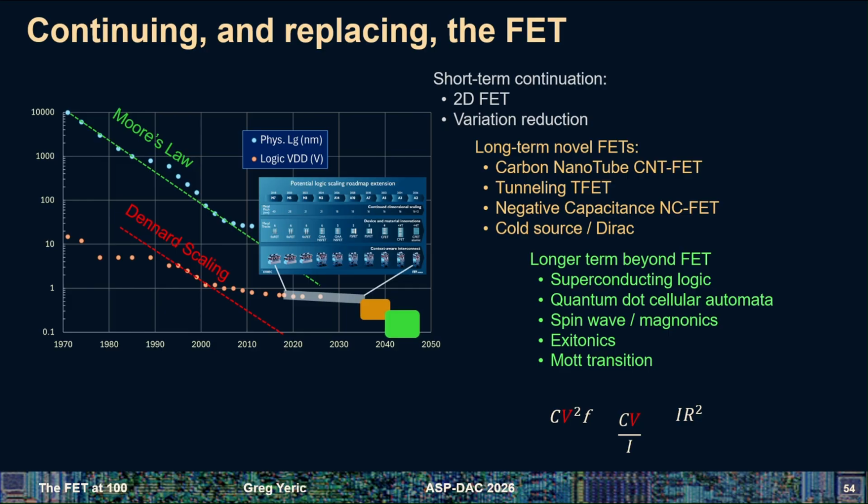Well, if the signal reduces by noise or other parasitic capacitances, things like that, you might not get enough signal out the other end unless there's gain. And so every time a signal goes through a transistor, it actually gets gained back up to a proper logic level, which we call in our modern designs power rails. So whatever the 0.6 volts and the 0, it's always 0.6 and 0 because the transistor gain is used to push the output signals all the way up to the two levels. You don't have that in some of these beyond FETs, and that's going to be a big problem.